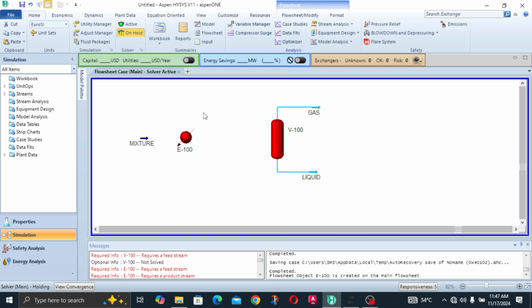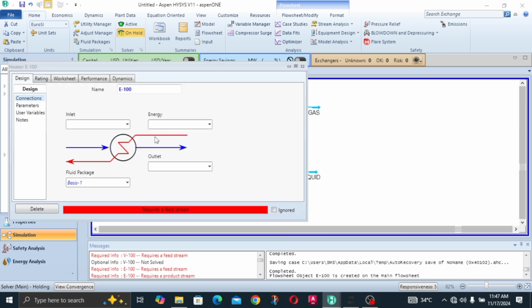That's the boiling point of hexane. And then at that stage, inside our mixture stream, we have a mixture of gas and liquid. The vapor fraction basically changes, and then we send it to a separator to do the separation of the two components. That's the hexane and water.